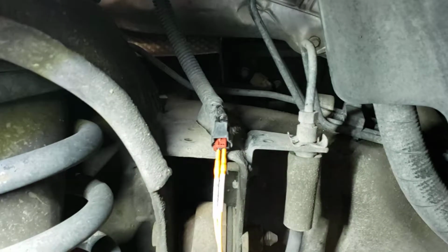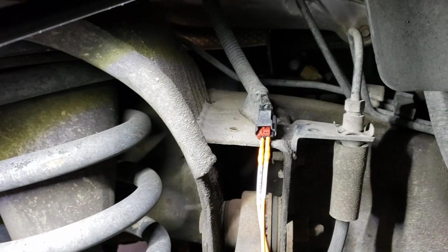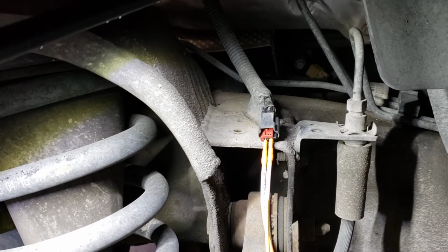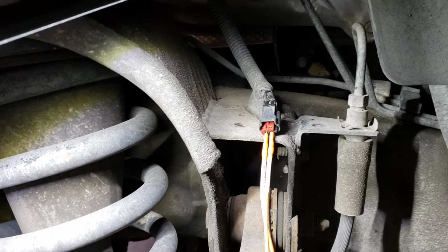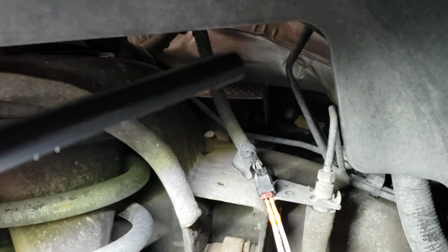Sorry about the glare. So I'm gonna do a wheel speed sensor check. So what I'm gonna do is, you got two wires going to the wheel speed sensor. Sometimes they're square wave, sine wave, triangle wave, depends. I'm gonna put these breakout leads in here and show you what this signal reads on the oscilloscope, and then we'll go from there. Let me show you how I have this set up.